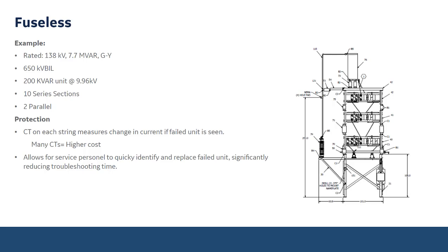The downside is you're using a CT for each string, so many CTs equals higher cost. But then you have to evaluate whether that higher initial cost will outweigh the benefits of the quick maintenance time.